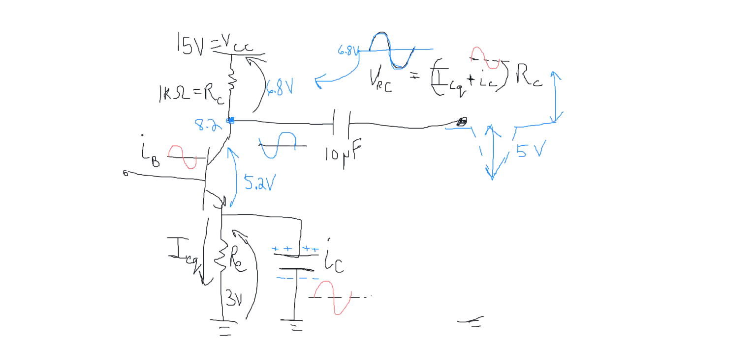That's a value of 15 volts. That's VCC. The node voltage here is going to be equivalent to VCC, because there's no current through this collector resistor anymore. But remember, there is current down here. So we have a total jump of 6.8 volts.